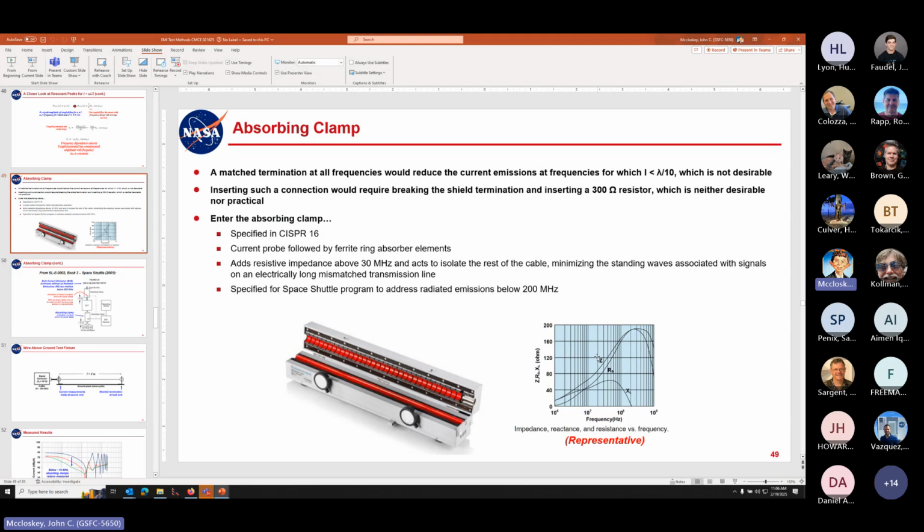The Z, the total impedance, is pretty much right along the same curve as the inductive reactance. So the inductance is dominating down here. Then as you get up a little above 100 megahertz, am I looking at that right? I'm sorry, 10 megahertz. Yeah, that's 10 megahertz, 10 to the 7th. So up around here, around 30 megahertz, is where the total impedance is dominated by the resistive component.